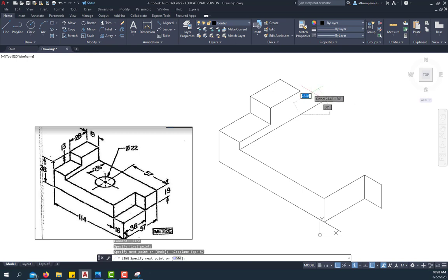So even though I'm not in the correct plane for it to go 90 degrees, OSnap will override that. So I could snap that line to this endpoint. I'm going to go ahead and hit F5 just so you guys can see my line going straight up and down, and I'm going to snap it to that endpoint. So what we've just established, we have this surface here, which is this backwards kind of L shape, and we have the corner that we can bring down to match up with these corners. So I'm going to do that now.